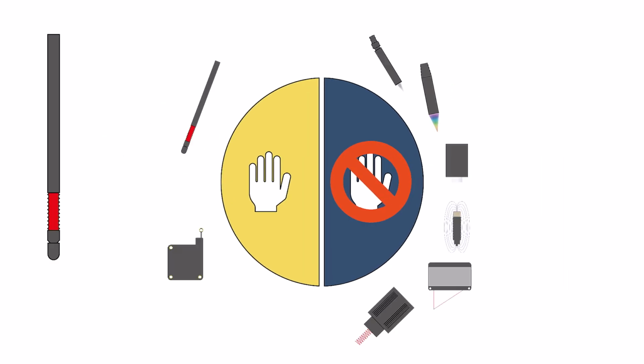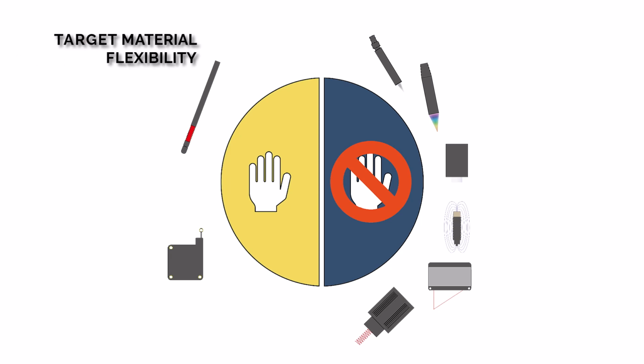Now let's start. From my experience, there are 3 distinctions that will help you to greatly narrow down the relevant sensor technologies for your application. The first and easiest one is contact versus non-contact. With contact-based solutions, some part of the sensor is either touching the target or directly attached to the target. This has the advantage that you can measure on almost any type of material. So for contact-based sensors, it's usually not relevant whether your target is made of wood, polymer, metal, or some other type of material. You only need to be in contact with the target.